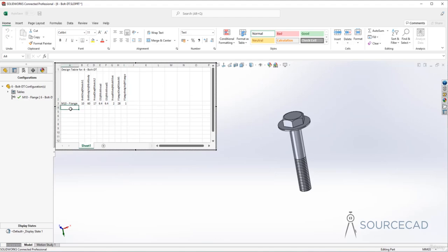Now here, I'll start adding just a few flanges. So I'll maybe type M12 and then M14 and maybe one for M16. So we've got these flanges added. Not actually flanges, but actually bolts added. Now here, to add all of these parameters, once again, we'll simply click the cell and just add it manually. So the first one is bolt diameter, which is 10. So M12 will have a diameter of 12. This one will have a dia of 14 and M16 will have a dia of 16.